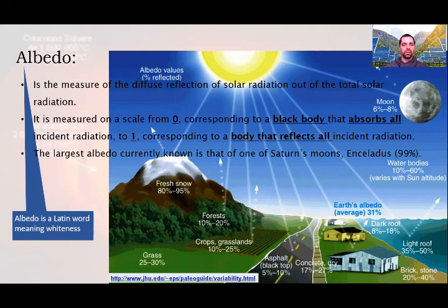At the front of the solar cell, there is a circuit path which works as a metal contact. This metal part has to be very small, but if it's too small, then the transition resistance between the metal and the semiconductor is very high because they are inversely proportional. So, although it is a small surface, it is shiny. And apart from its reflection effect, it also casts a shadow. But for shading losses, a bad system placing is much more dangerous.